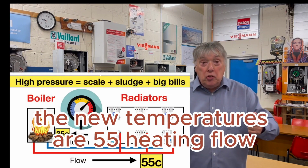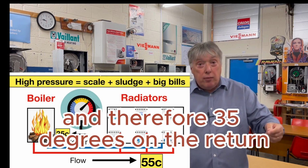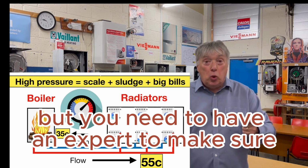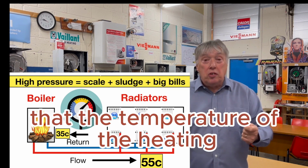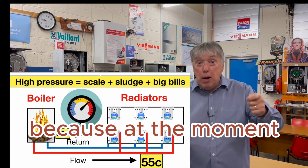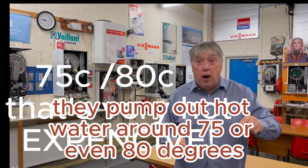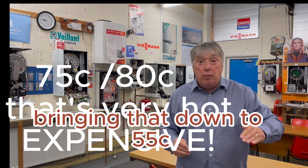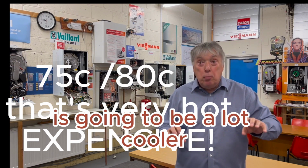The new temperatures are 55 heating flow and therefore 35 degrees on the return. But you need to have an expert to make sure there are no accidental or incidental consequences, that the temperature of the heating is going to be a lot lower, because at the moment most boilers, they pump out hot water around 75 or even 80 degrees. Bringing that down to 55 is going to make a huge difference to the temperature of the radiator. It's going to be a lot cooler.